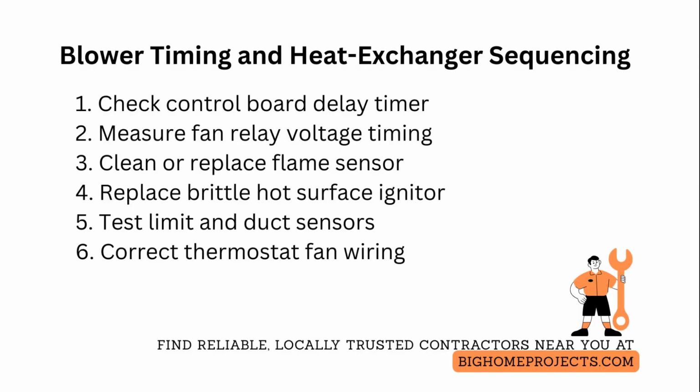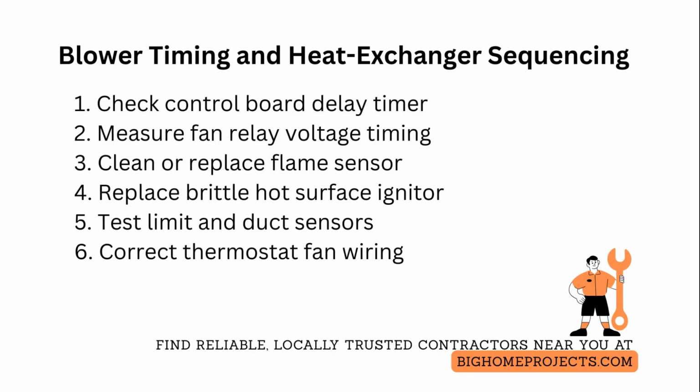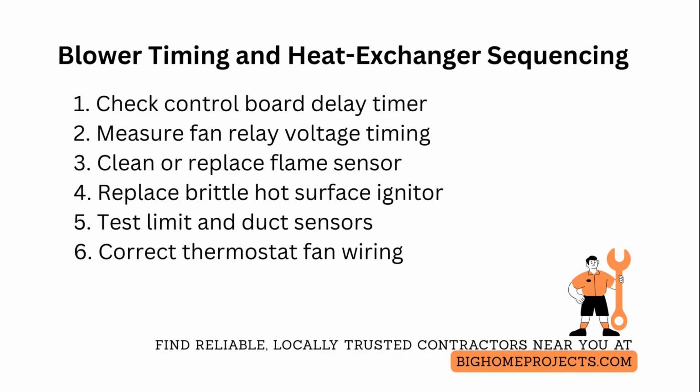If the control board is old, consider updating to a supported board that enforces a reliable blower-on delay and improved flame sensing logic. Always shut power and gas before working, follow the service manual, and if you are not fully comfortable with live electrical and gas components, hire a licensed HVAC technician to avoid safety risks.